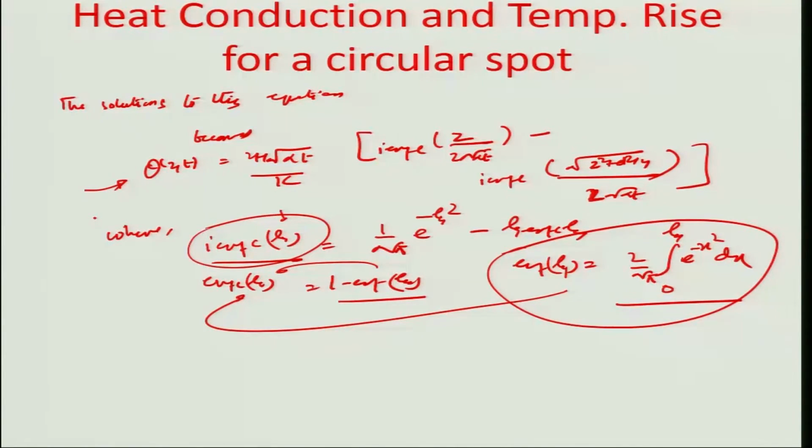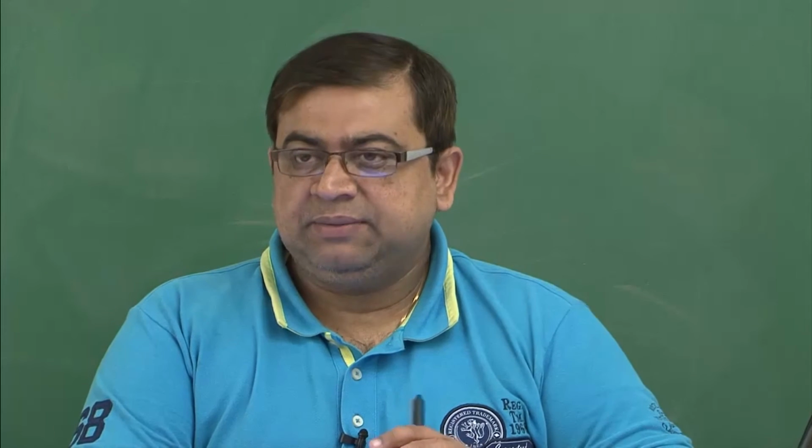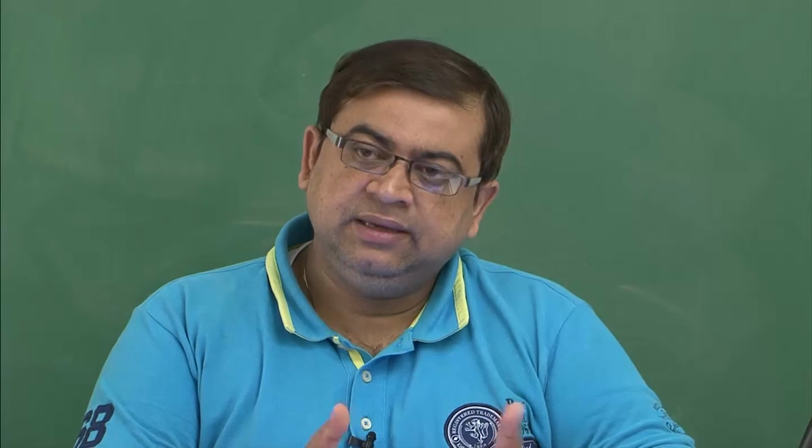So with this I would like to close today's module, but we'll investigate this more in a later module, where we talk about a circular spot and actually couple energy and try to see if we can calculate or estimate the depth of melting temperature and what is going to be the zone and extent up to which theta is equal to theta m, so that we could construct the zone of machining for a laser spot.